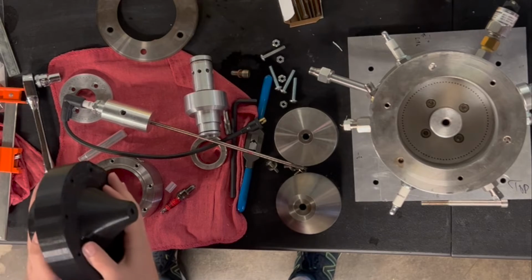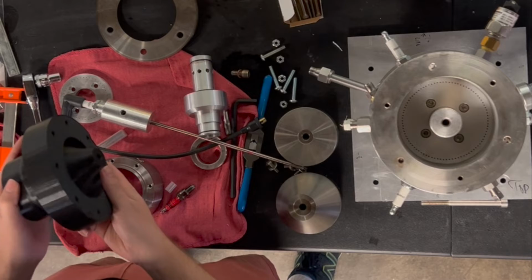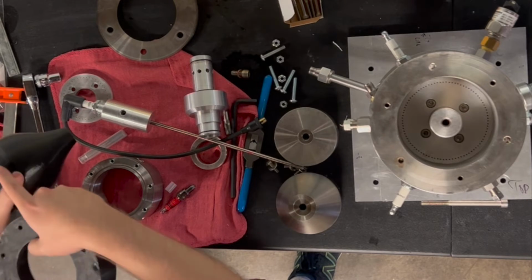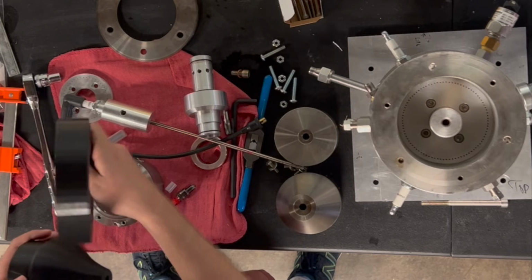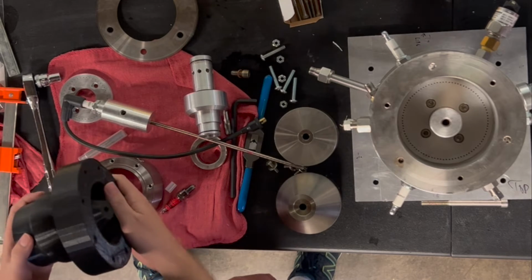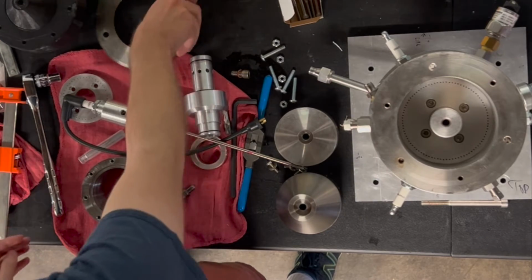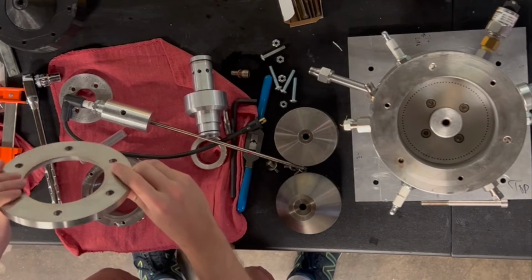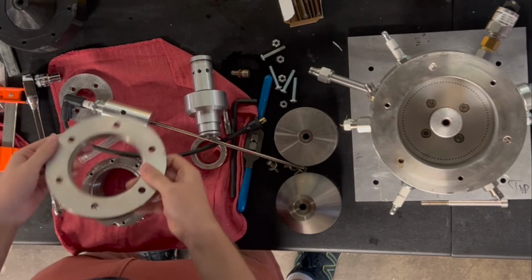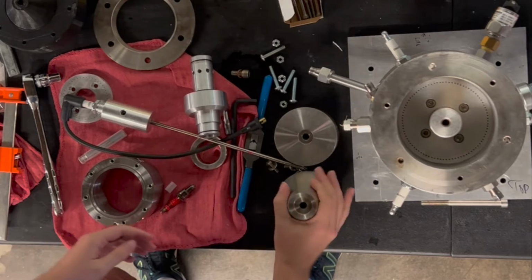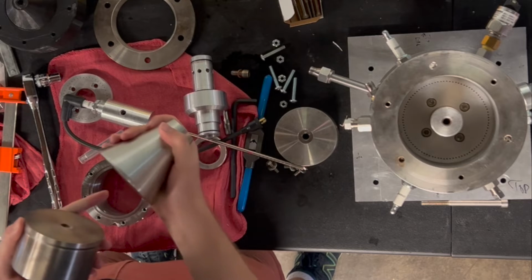So here's our starting point. It is a simple 3D printed model of a nozzle based only on area expansion. We've got a spike which includes the choke and the curve, and then we have a lip which sort of fits conformally around the spike right there. The ones we actually made and tested out of stainless steel, we have the lip right here, which provides just a flat sort of lip around the outside of the engine, and then we also have our nozzle, which provides the shape, and our choke plate, which provides the choke, and these are separate.